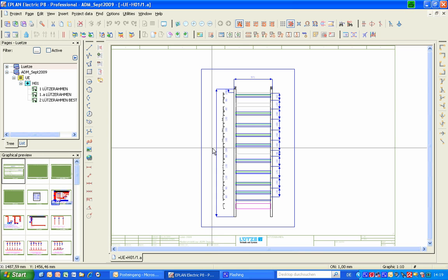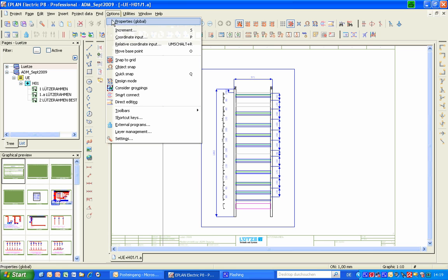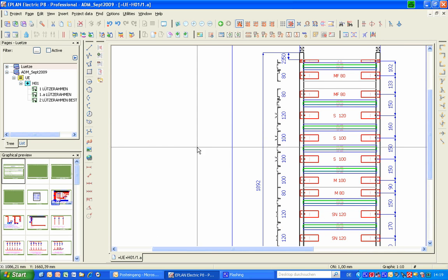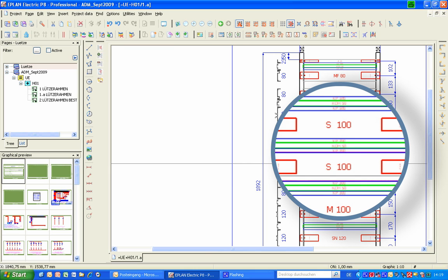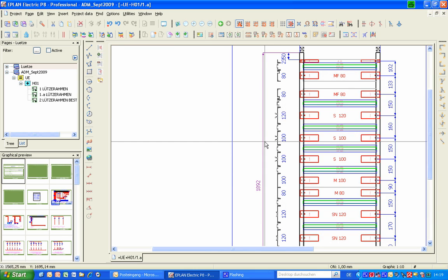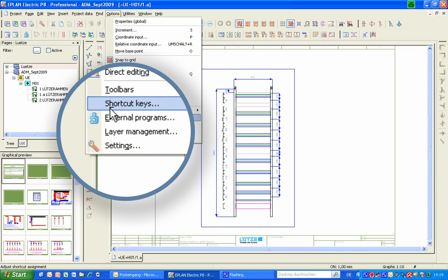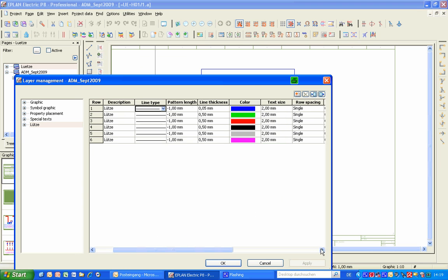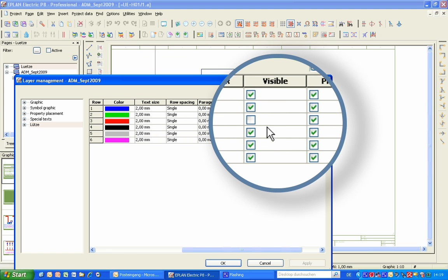With the drawing options integrated in Program P8, the frame thus displayed can be modified. For example, you can zoom in on the frame. In Frame View, you see the brackets, the rail type, the corresponding comb and cover profiles, and you can also see it all in Page View. Via the layer management, the bracket and rail designations can be masked out to create a text-free space for placement of the devices.